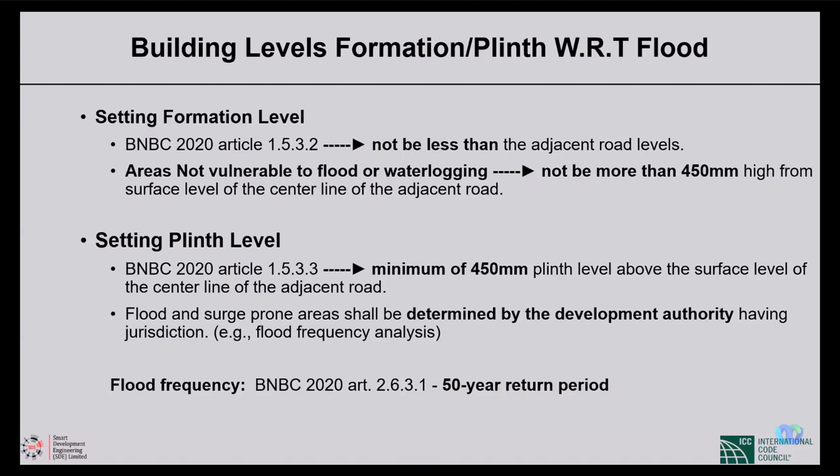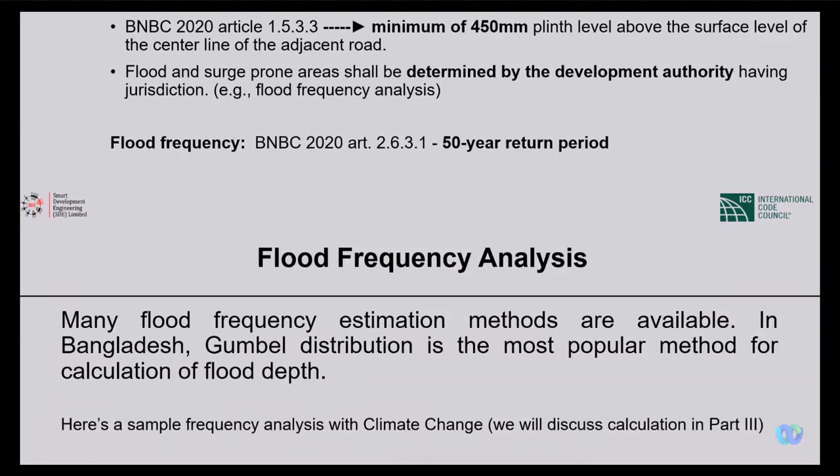And with climate change, a 50-year return period might come in 30 years. So you have to understand which return period, how long the building lifetime is, and within the lifetime, what return period you are looking at, with the external changes or consequences in the system.